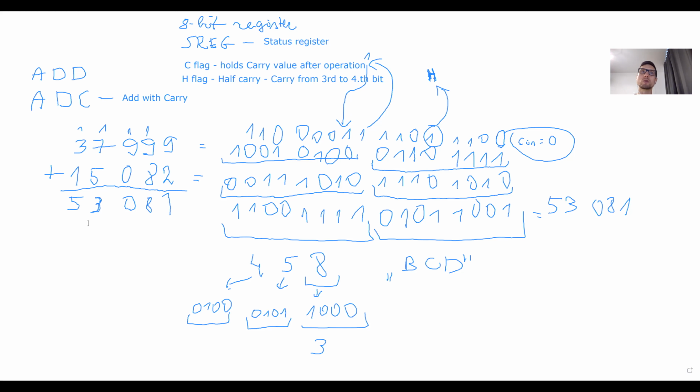So I can just write with text. To add, for example, a 16-bit number on an 8-bit system, add the bottom 8 bits with add, then the top 8 bits with ADC.